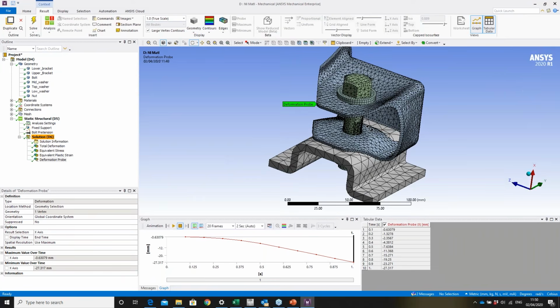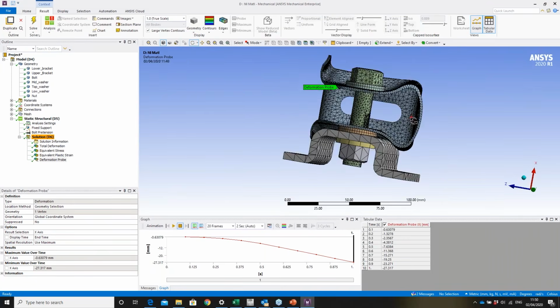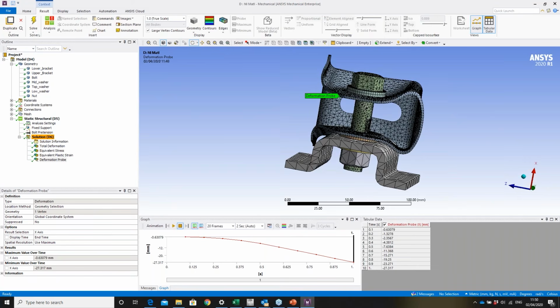So for instance, if you think you're not interested in having opening and closing on these washers as I have here, then leave it as bonded contact. Don't switch on nonlinear geometry unless you know or suspect it makes a big difference in the results. Always try and keep your analysis linear to keep your run times and computational overhead down.